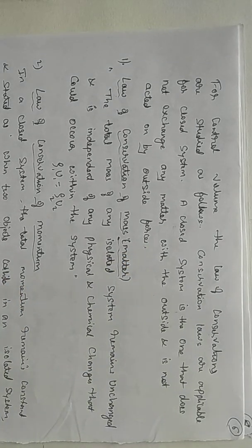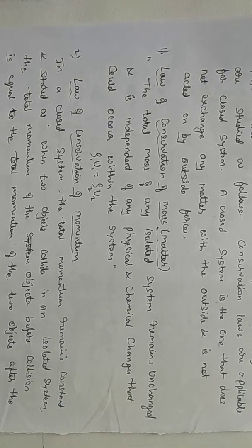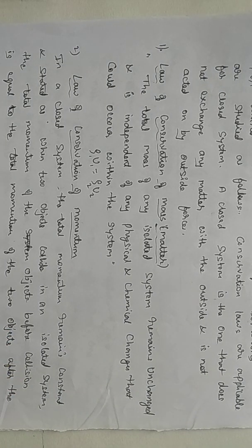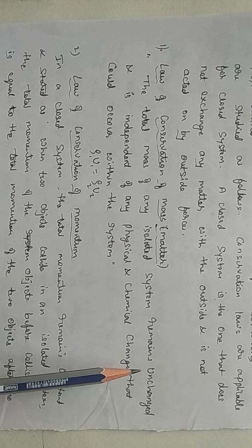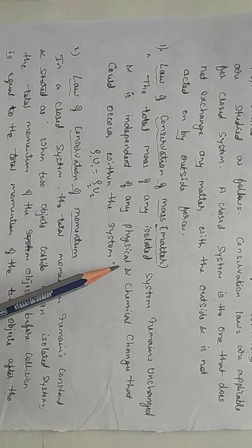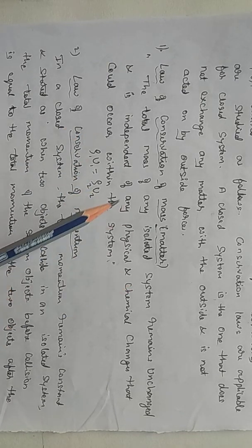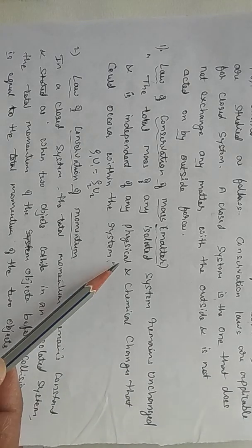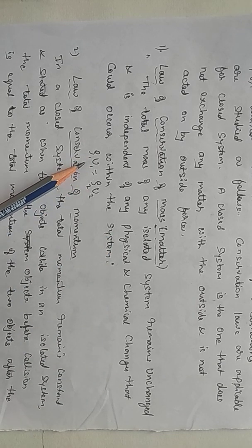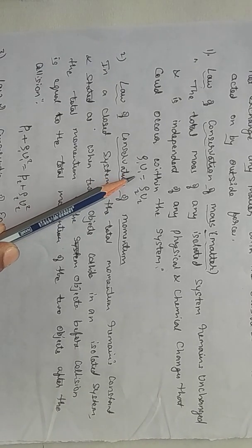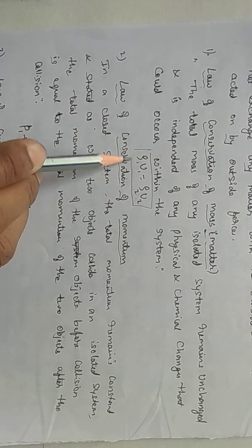Now with this, we are going to apply the laws of conservation of mass, momentum, and energy. The law of conservation of mass we have studied in our PU. What it states: the total mass of any isolated system remains unchanged and is independent of any physical or chemical changes that could occur within the system. So the mass is conserved, irrespective of the physical and chemical changes that take place. It is given mathematically by ρ1u1 = ρ2u2. This is in connection with the conservation of mass.